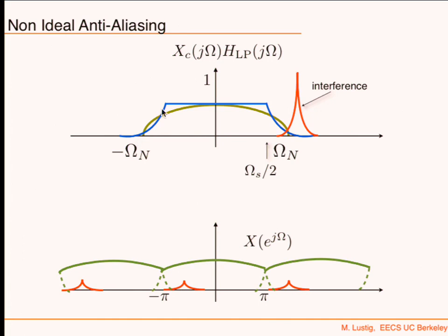And it's not perfect within the band. It's not going to be completely flat, and you might have an interference on the side of the band that may not be attenuated absolutely. So you will get both distortions of your spectrum, weighted in phase and magnitude by the response of the anti-aliasing filter, as well as some aliasing that's still going to occur. Okay, so that is always there.